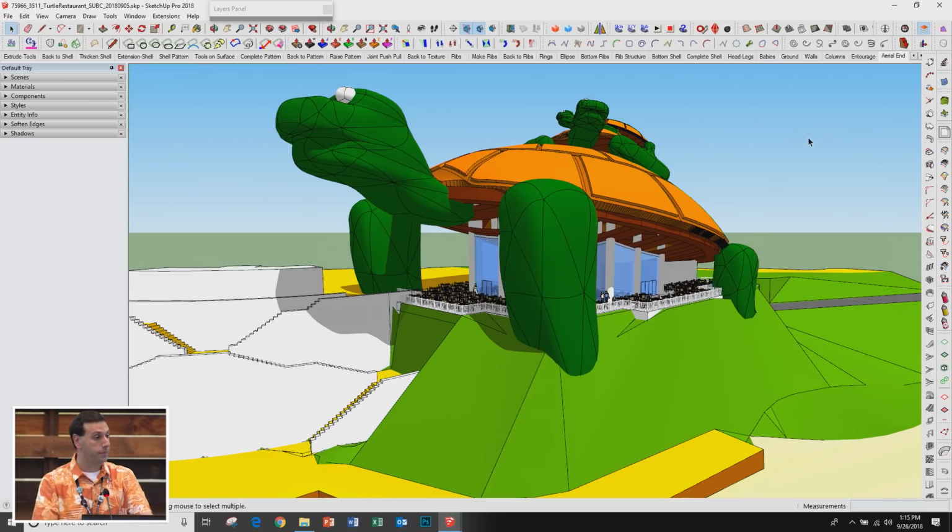So the success of this project comes from the Shelley system. Initially, you had some curves. Yeah. How did you get those curves to perfectly be rigged so that when you create the surface, it's nice and smooth? I basically just drew like I had the column line, and so I drew a plane at that column line, and then I just drew an arc from this column to that column, so I had a nice smooth arc. And I turned up the precision of the arc pretty high. It's still faceted. All the arcs are faceted, but I just turned up the precision pretty high.